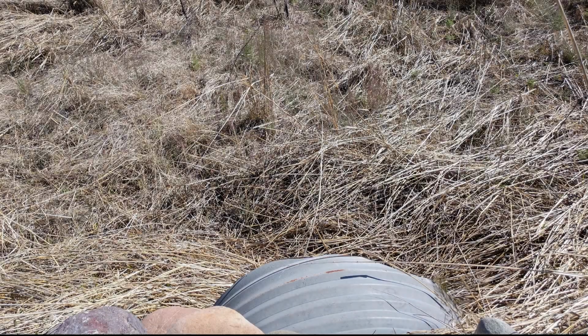I have seen where traditional culverts have stopped head cuts from moving upstream. This is why one should use great caution when replacing a culvert with a bridge or a bottomless culvert. The last thing you want to do is to provide conditions where a head cut can move under the road and destroy the wetlands upstream of the road.